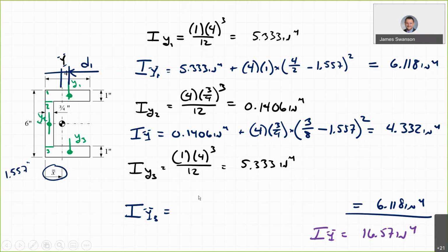All right, so parallel axis theorem. And if we wanted to, we could rework this problem yet a different way. We could go in and use the positive and the negative area on this one as well. But if we did it for the y-axis, we would have to use the parallel axis theorem with the negative area and with the positive area because those axes don't line up. So I won't do that, but we could if we wanted to.